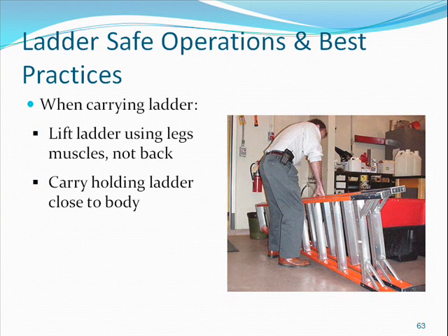When carrying a ladder, lift using your leg muscles, not your back. Carry the ladder holding it close to your body. After a thorough inspection, your ladder is ready for use. However, be sure to transport it safely to your work area.